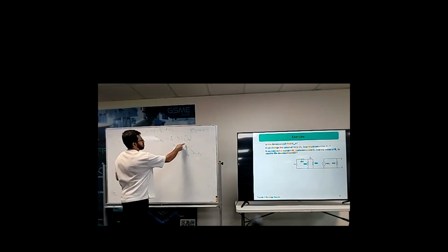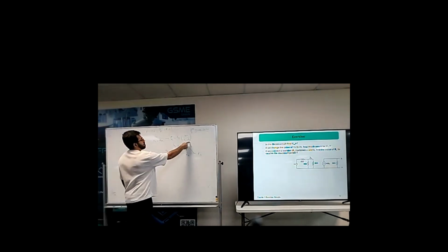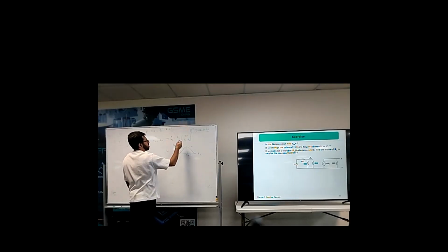Derivation of this equation. And how much is the power? That's the maximum power. How much is it based on the formula? These are equal RL, yeah? That means 2RL squared, 4RL squared, and one of them should be simplified by RL, which is VT squared over 4RL. This is the maximum power RL can get from this circuit.